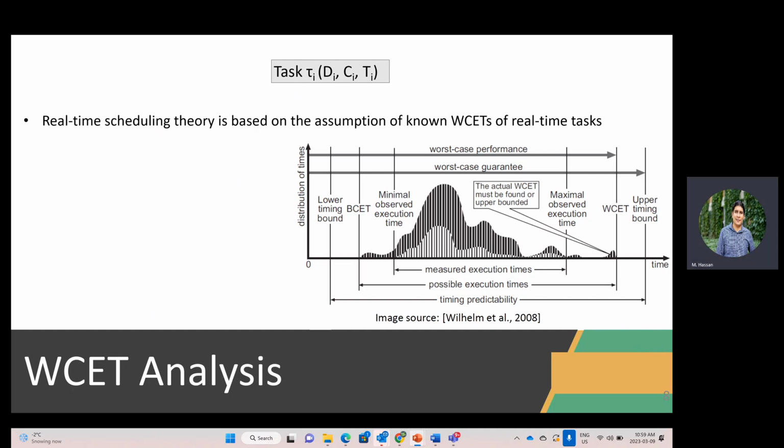What would we do for those tasks? Because we still have very complex tasks in every realistic embedded system. What they do is what's called empirical timing analysis, or measurement-based timing analysis. To satisfy the certification requirements, I take my task set and my hardware, my car for example, and run it millions of times under all possible conditions.